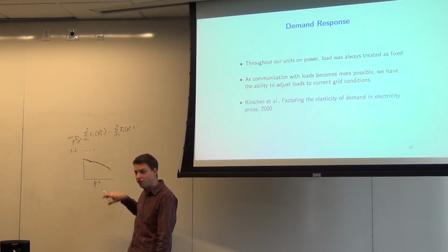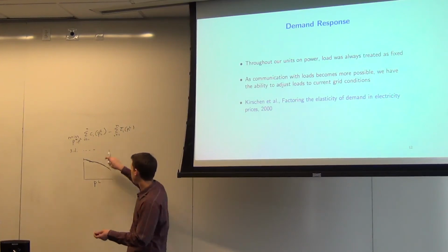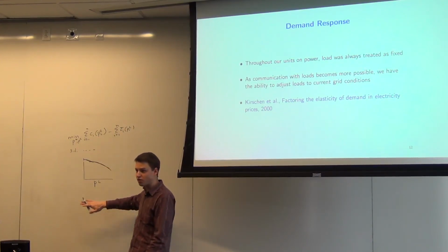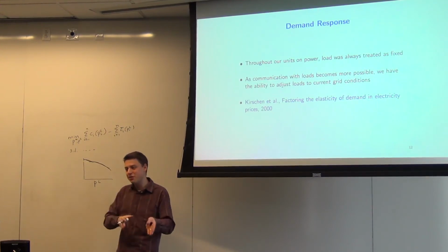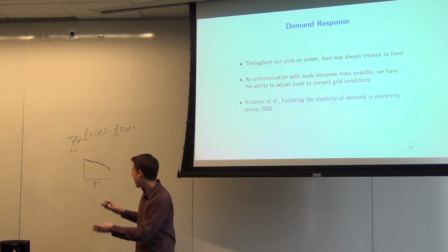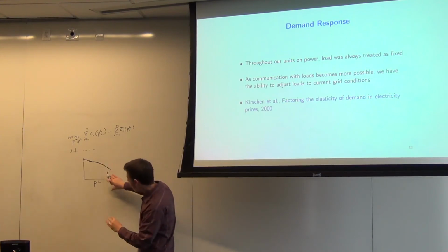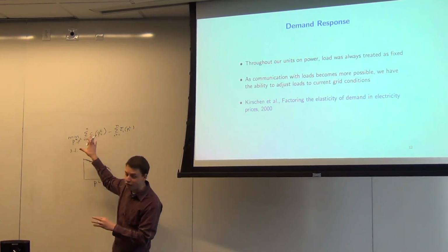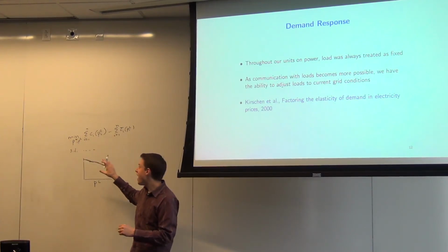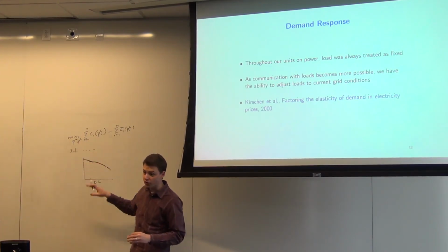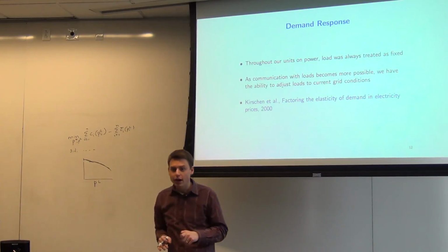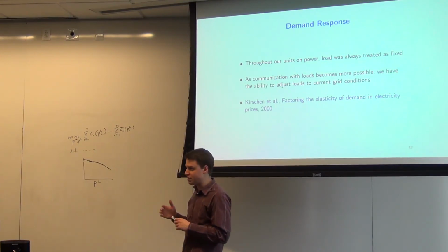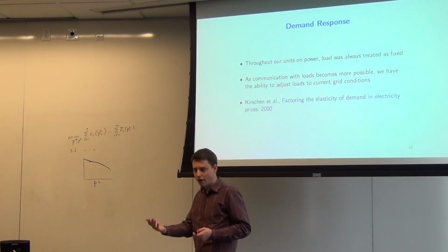But under that formulation, you can now optimize. And of course, we also have constraints on this too. We can't shut off load entirely. We have bounds on load just like we have bounds on generation. So we can now optimize our same optimal power flow problem subject to the fact that load itself is a variable in our problem, and we can control it to a certain degree. And this will change everything. I mean, not everything, but it changes the things you expect about optimal power flow.